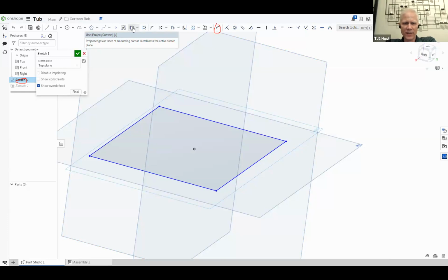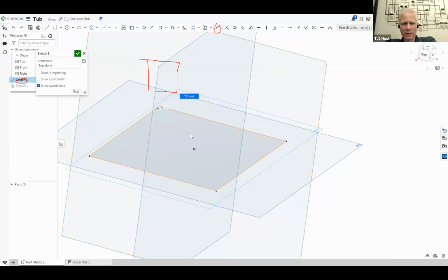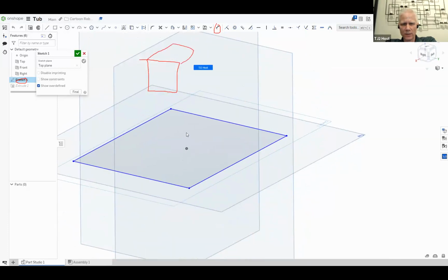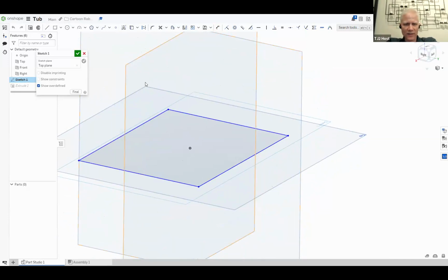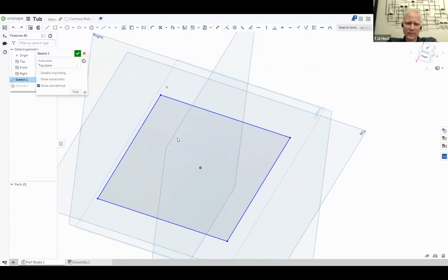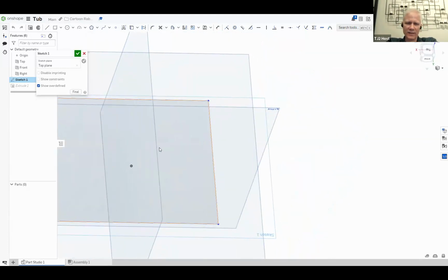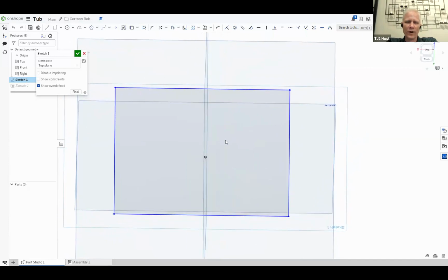So make a big block that was the dimensions you wanted, and we'll hollow it, and then cut off the side after we get done. So you've got the dimensions that you want this to be. Let's make it 24 inches wide. It'll be only a 1/2 inch shorter than the robot is wide.